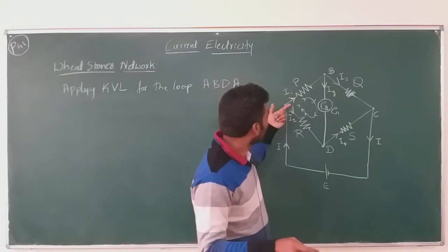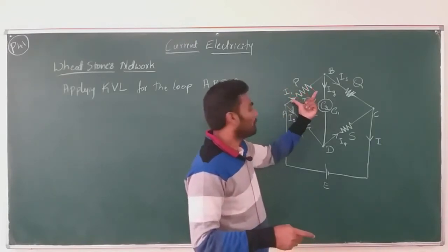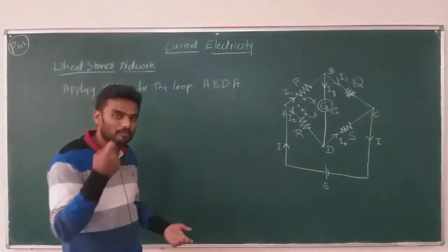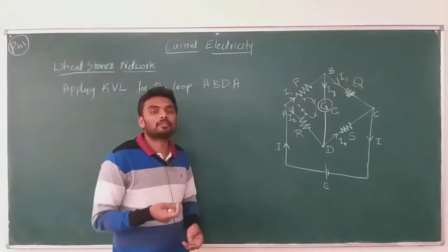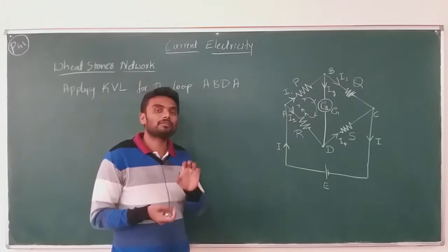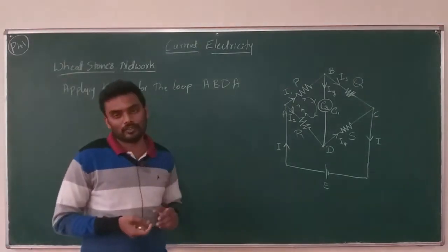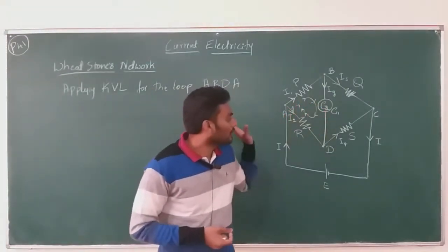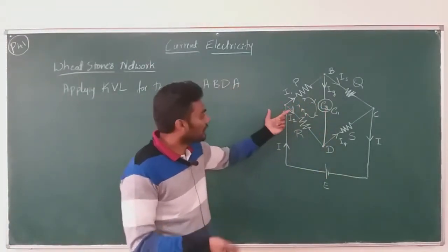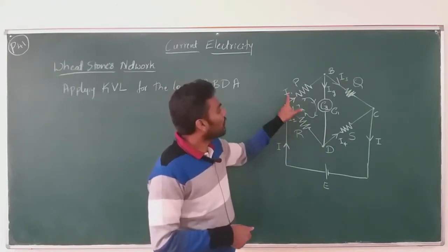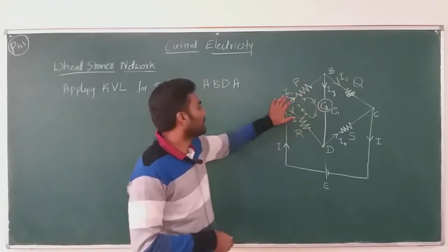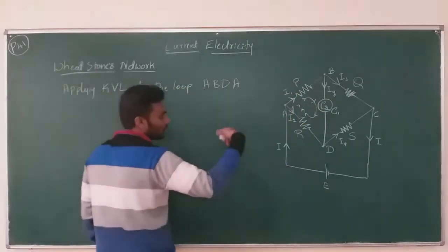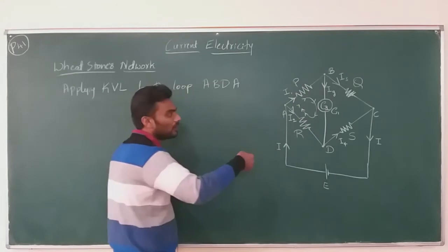So, now I should take I1 P, because you know very well the Kirchhoff's voltage law says sum of EMFs in the network in a loop is equal to sum of product of current and resistances, right. Since there are no EMFs here, the EMF part will be 0 and the other part left will be simply the product of currents and resistances. So, let me go with the actual formula, the actual definition of KVL.